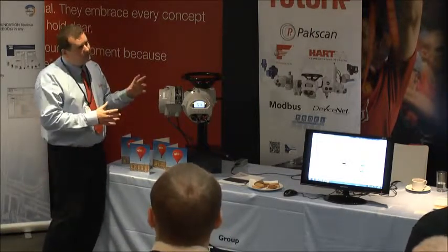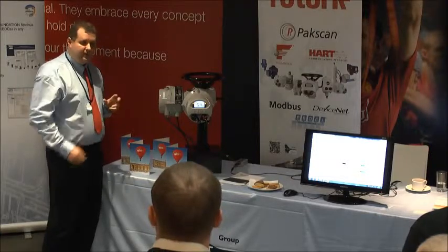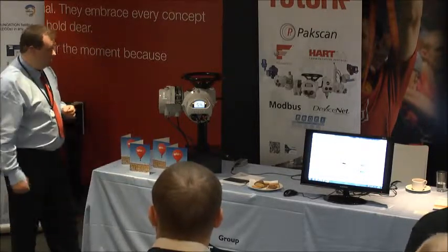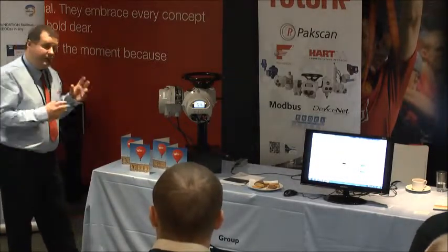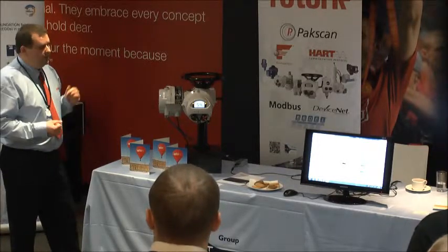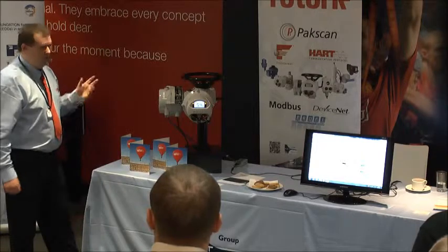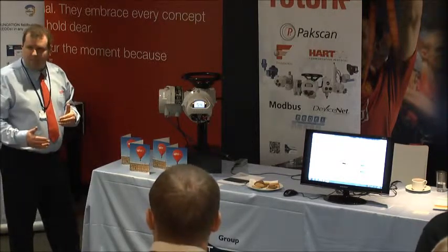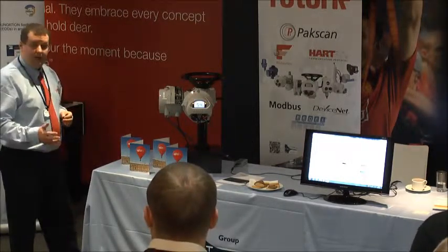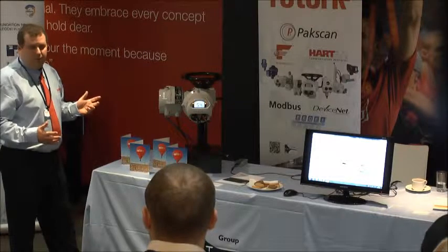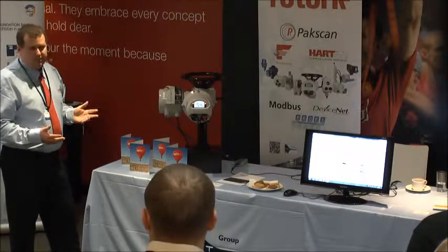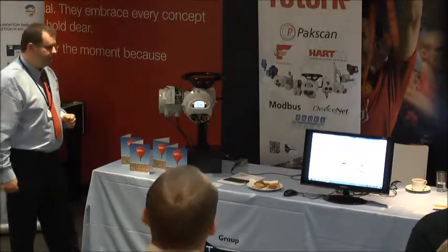So you can compare that to when it was new, and that will give you an idea of when your valve may need maintenance. So the idea is that you can schedule that for a time in your process where it's easy to pause production, say in a month's time, rather than waiting for 2 months and then suddenly it becomes jammed, and at which point you have to stop your process.